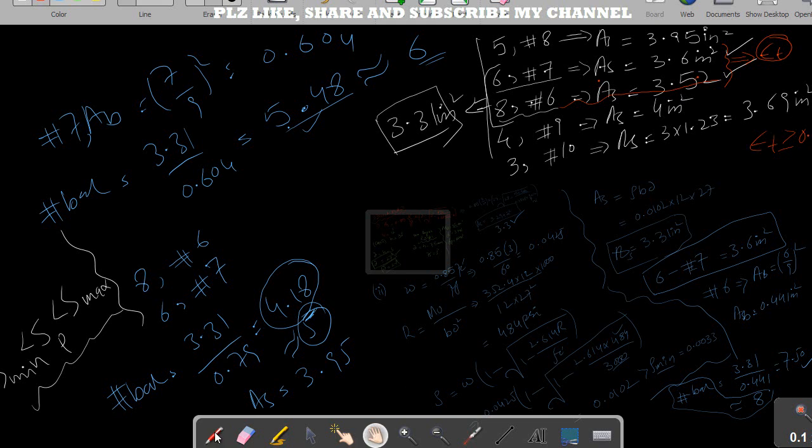Similarly then the phi value will not remain as 0.9, because if epsilon t is not greater than 0.005, then the phi value will not be equal to 0.9, and we have to calculate the phi value. So that's why always choose a bar area which is close to the calculated value, right? Thank you for watching. See you in the next part.